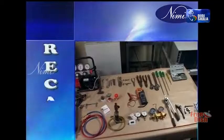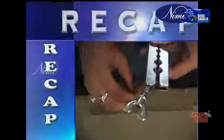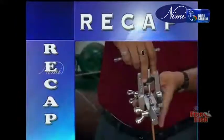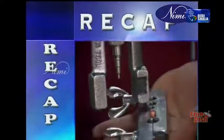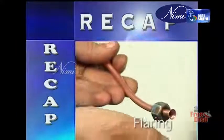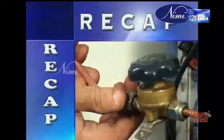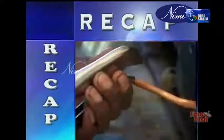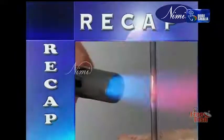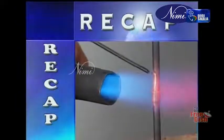These are the common basic tools for this purpose. Swaging is a means of shaping copper tubing, accomplished with a punch type or screw type swaging tool. Swaging permits two pieces of soft copper tubing of the same diameter to be joined together without the use of fittings. Flaring: when connecting tubing to fittings, it is a common practice to flare the end of the tube. A pinch-off tool is used whenever it is necessary to seal off copper tubing. We can make a good leak-proof joint as it is showing.